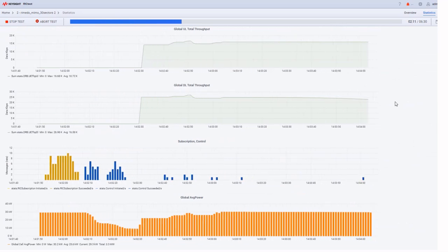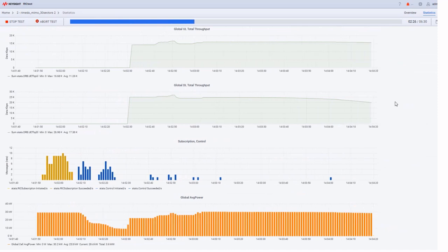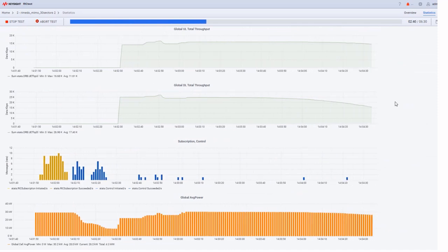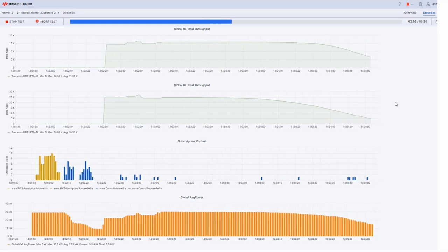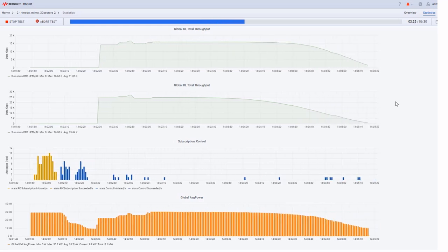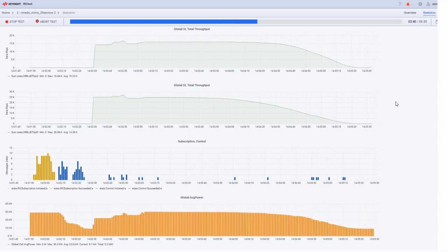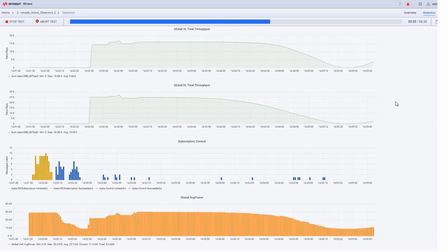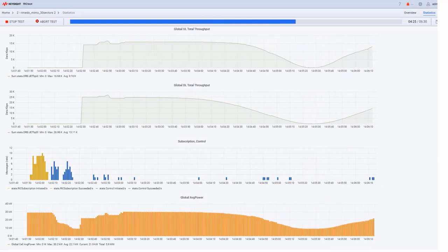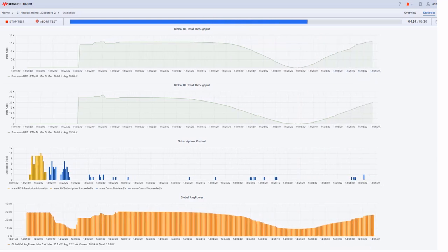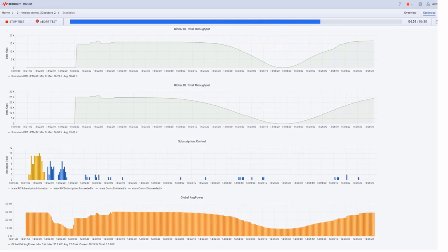Here we see subscriptions and control messages. These control messages are being applied and are doing RF channel reconfiguration for reduced energy consumption. These control messages are sending configurations for half panel and for quarter panel opportunistically as appropriate for its algorithm.